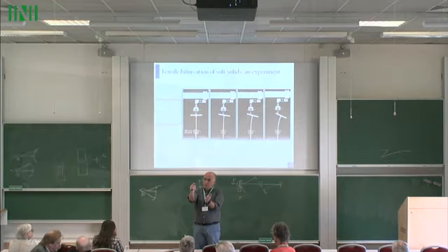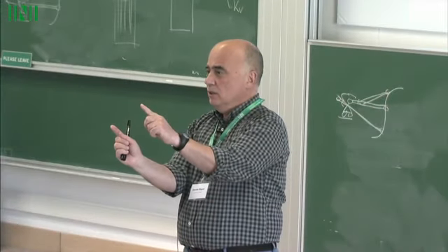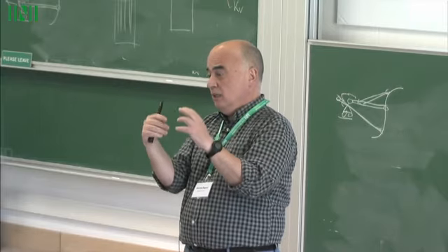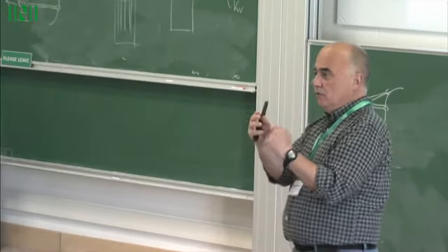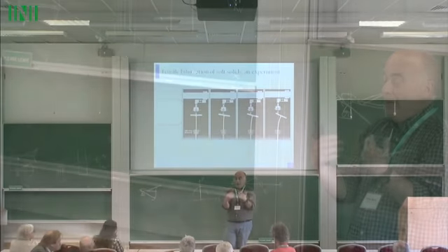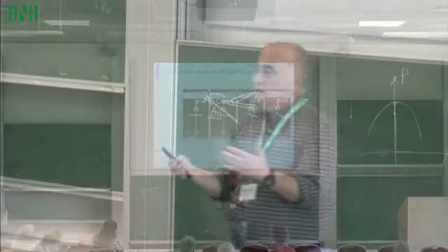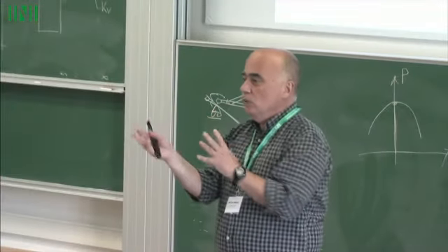One is the length of the shear band, and the other is the distance. So playing with these dimensions and playing with the wave frequency, of course we can induce situations where the resonance is important because in that situation the shear bands will grow fast, they will touch, they will merge.